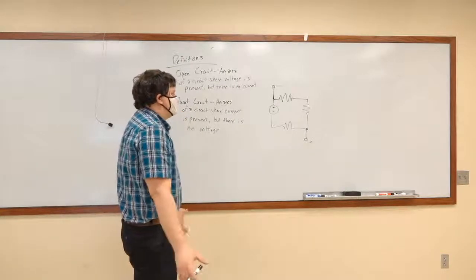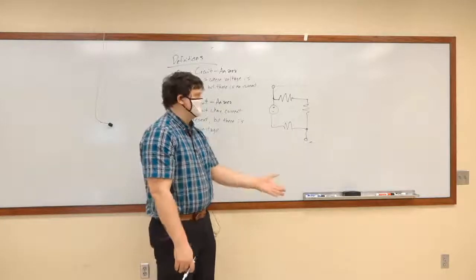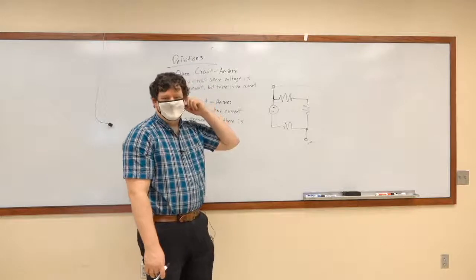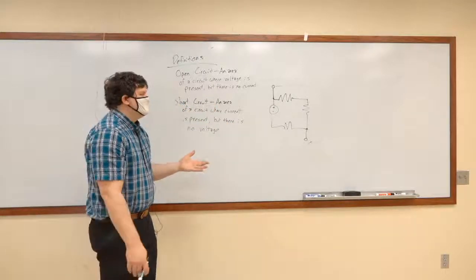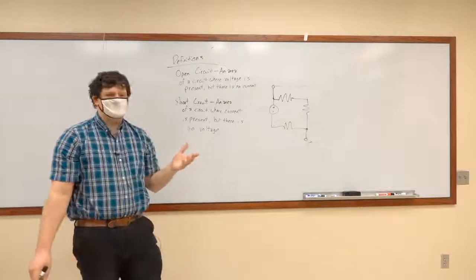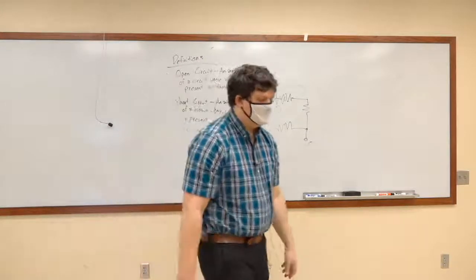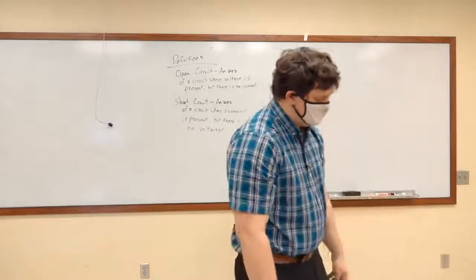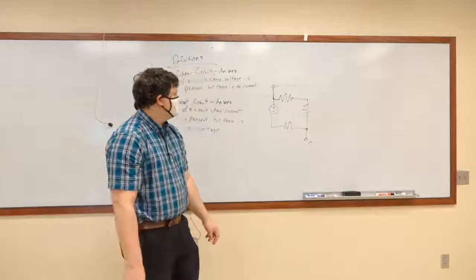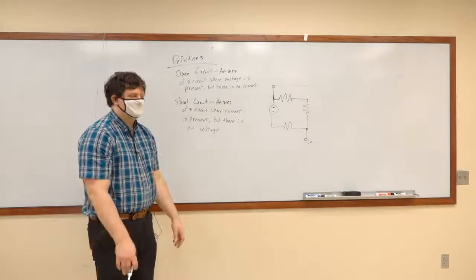You can do that with anything. An open circuit can exist anywhere. And we can pull an open circuit voltage out of anything. One of the reasons why I had you calculate nodal voltages is because understanding nodal voltages will allow you to understand what the voltage is in that open circuit.